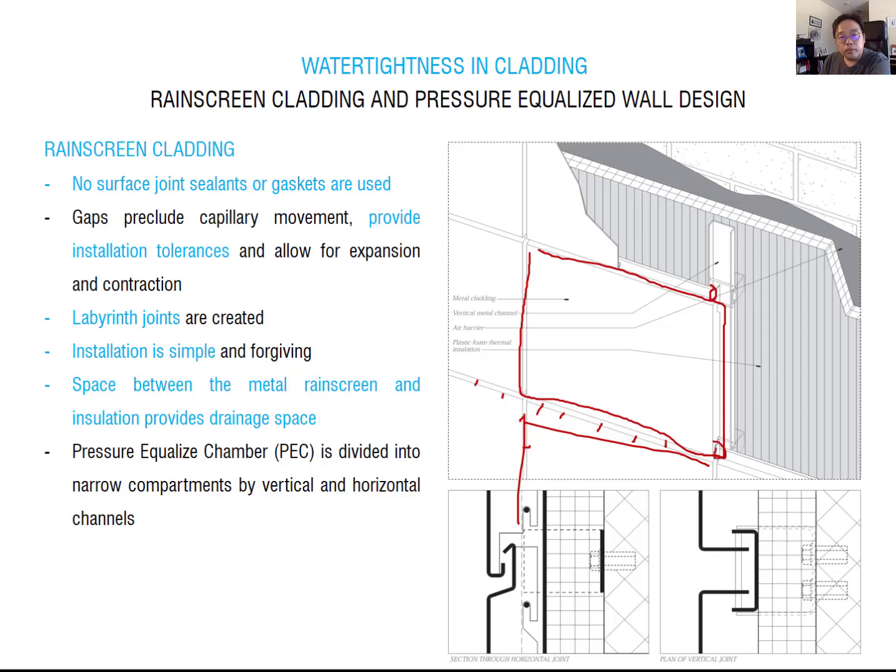But remember, when you don't have any sealant, you have to consider the different forces. In this case, you can consider using two different approaches for your panel joint. First one, panel to panel, you can consider using this labyrinth joint. This labyrinth joint is interesting because it applies all different force factors. First, the inside is higher and the outside lower.